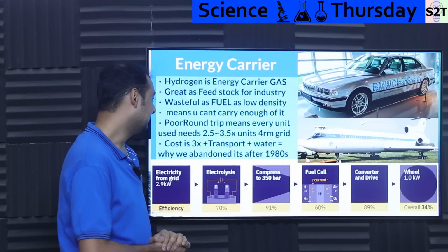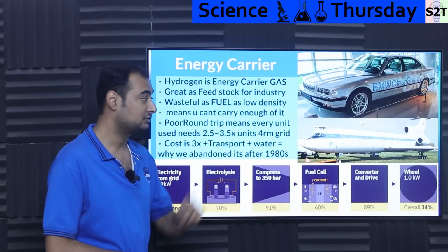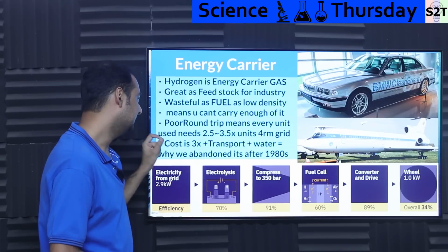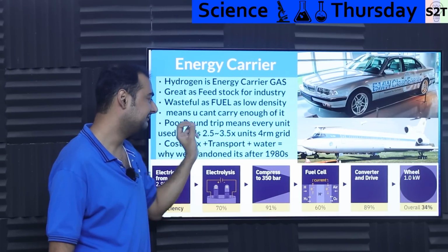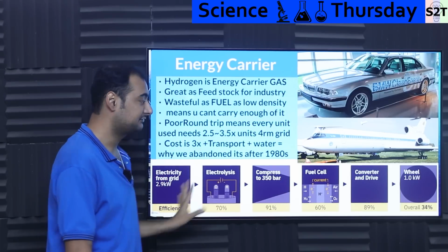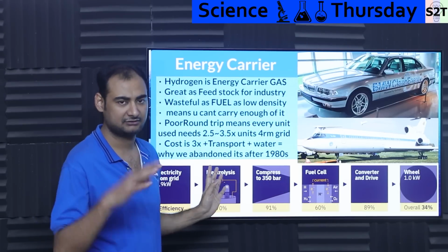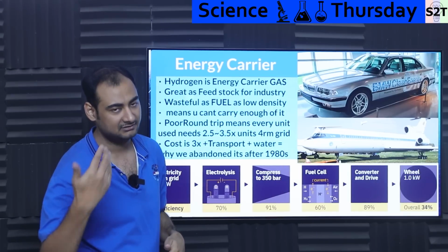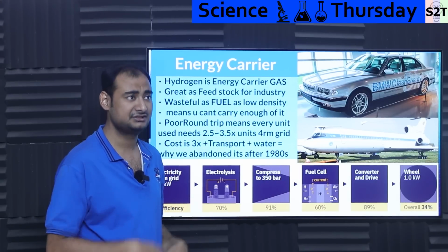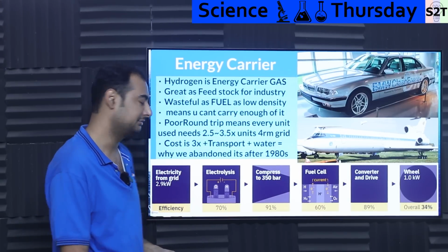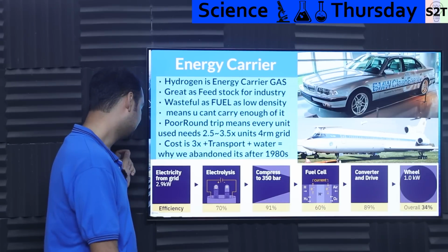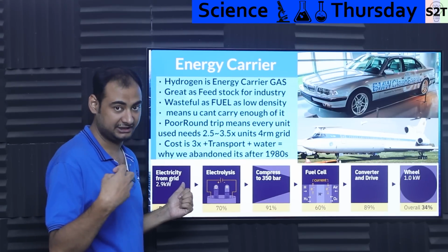So that's there. Now, round trip efficiency, what does that mean? That simply means to give you 1 unit of power into your wheels, you have to pay around 2.5x to 3.5x. For example, this is from Britain. They're thinking, what if we did a hydrogen train? They did the whole math and research. Be mindful, the same thing is available in Germany also, if you can read German. I do not read German, so I'm using the UK data point. And again, the same data point is available in every encyclopedia. So 2.9 units of energy you have to take from the grid.